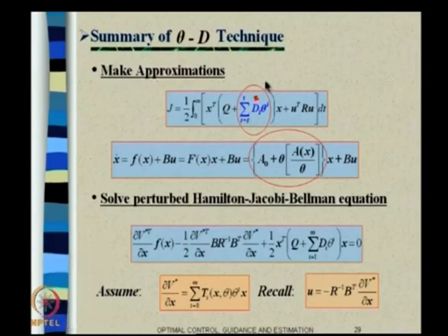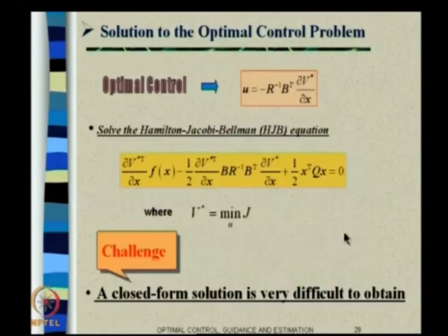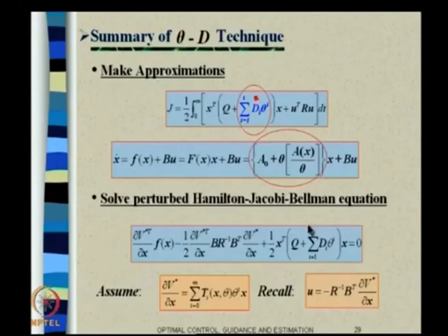So what you are doing is perturbing the cost function a little bit and modifying the system dynamics a little bit as well actually. Then it turns out that if you take this HJB equation and substitute that, then instead of q you have to substitute this expansion actually, whatever q plus this expansion is there, and this turns out to be like that. Now here is the trick.